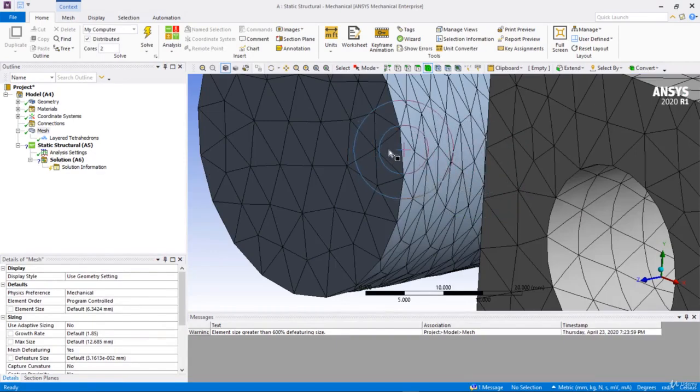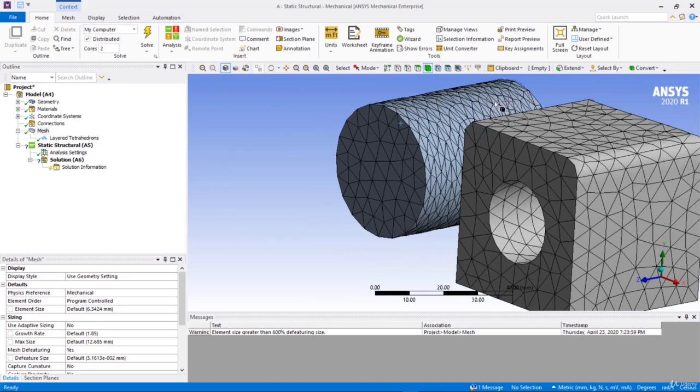But what will happen is, here instead of arbitrarily generating based on the shape and geometry, it will select a surface, and on that surface it will generate tetrahedrons, and based on that it will be placing tetrahedrons layer by layer. So one layer after another layer it will be placing until it is able to complete meshing of the entire geometry. And I hope you had a little understanding of hexadominant meshing methods and tetrahedral meshing methods.